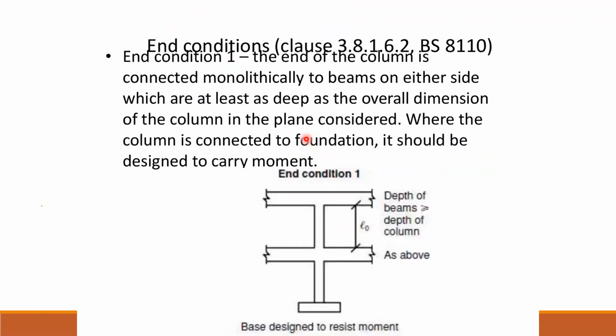End conditions clause 3.8.1.6.2 in the BS 8110. End condition 1, we studied a little bit more. The column is connected monolithically to the beams on either side, which are at least as deep as the overall dimension of the column in the plane considered. Where the column is connected to the foundation, it should be designed to carry the moment.